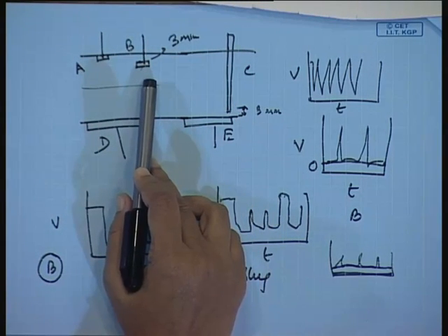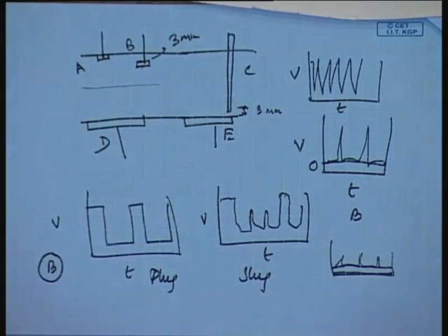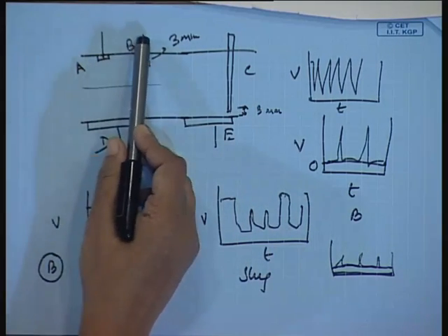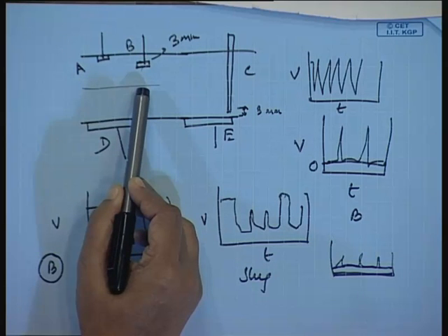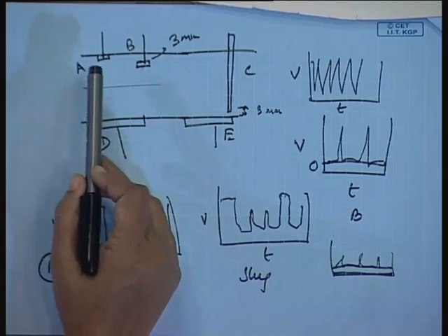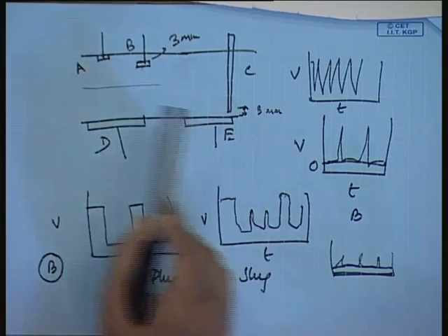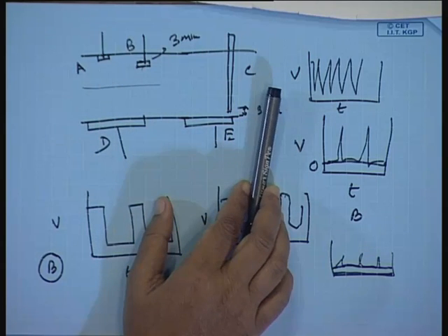If we are dealing with vertical pipes and not horizontal pipes, then there are just four flow patterns: bubbly, slug, annular, churn. There you do not need three probes. What you need is one wall mounted probe, and one probe probably located at the center. That will give you the difference. So, depending upon the application, you are going to decide the number of probes, the location of probes, and the design of the probes which you need.